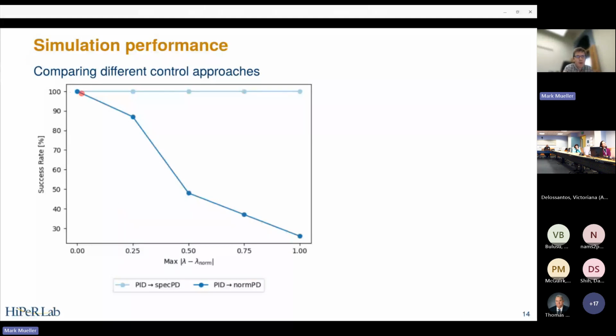And this is for these randomly generated vehicles, where we plot on the x-axis the deviation from some nominal vehicle. A nominal vehicle is a vehicle that lies in the center of the range that we have defined. There are 2 lines that we're seeing here. The light blue line is the performance if I had access to the true vehicle parameters in each case, and I designed a model-based controller with those true parameters in mind. And of course, what I expect then is perfect performance, and that's what we see here. So if I knew the true parameters of my vehicle and used our model-based control design approach, you would be able to control every vehicle.